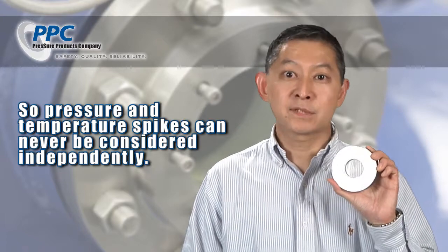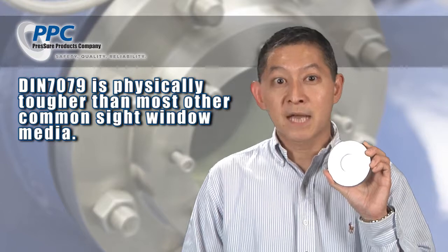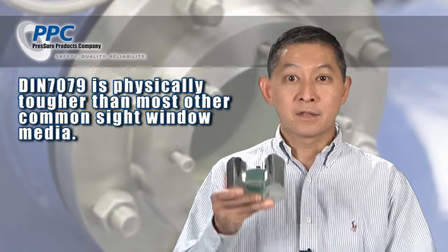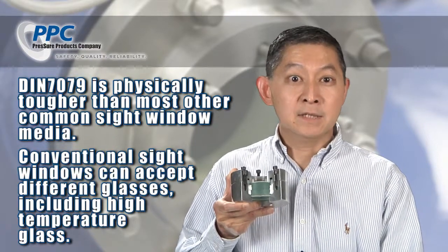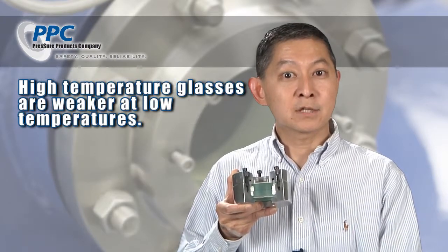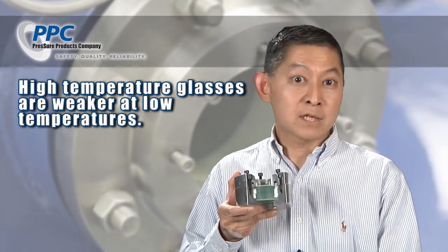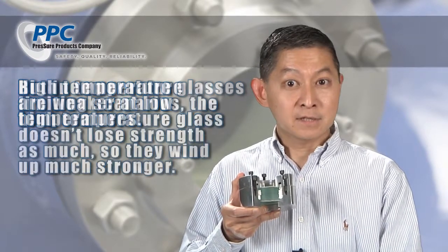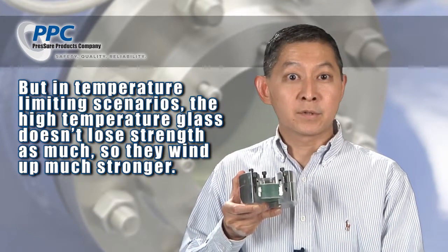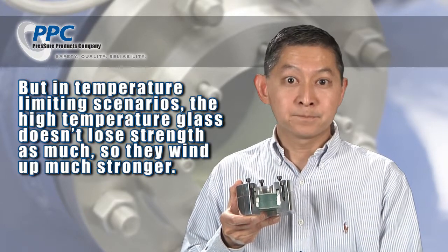This is our DIN 7079 compliant fused glass product. A lot of vendors, including us, advertise as being stronger than other sight glasses and therefore safer. This is our conventional product, and it's capable of taking high temperature glass lenses. These high temperature glasses tend to be soft with low tensile strength numbers, so we do not normally advertise them as being strong. However, in this scenario, where the risk factor was temperature, this conventional product with a soft high temperature glass offers a much larger real margin of safety.